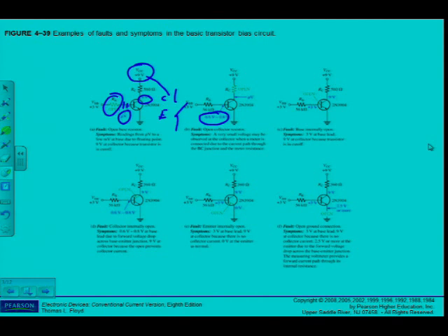approximately 0.7. They show here, it's not exactly, of course now we're doing practical, 0.6 to 0.8. It may even be a bit more or a bit less. But it's not an accurate voltage, but I do have a floating point at the collector. So the same as I had in the previous one with the base resistor, it could either be the collector resistor that's open or the track that's broken before the collector's terminal.